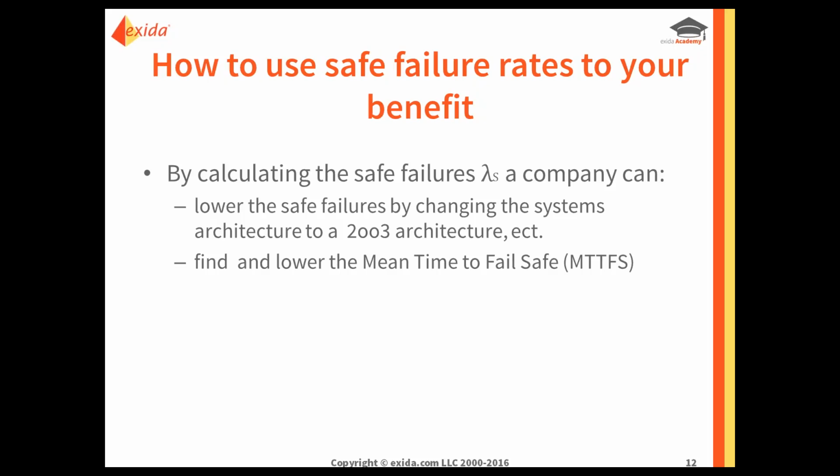And unfortunately, this happens more often than anyone would like to really acknowledge, especially in the functional safety world. Sometimes it can be a simple bypass like rewiring something or pulling wires out. Sometimes it could be bypassing by getting some piping and routing it around. Or sometimes, once we saw it bypassed by a piece of wood actually, and they just stuck the piece of wood in the gate valve and it prevents it from shutting. And yes, I guess that's one way to make a gate valve stay open. Is that the best way to make it stay open? Probably not. I'm sure that there could be a million better ideas, but it happens.